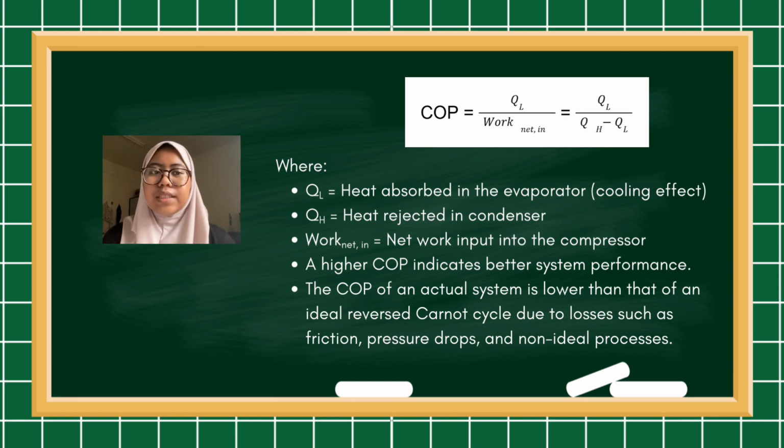A higher COP indicates better system performance, and the COP of an actual system is lower than that of an ideal reverse Carnot cycle due to losses such as friction, pressure drops, and non-ideal processes.